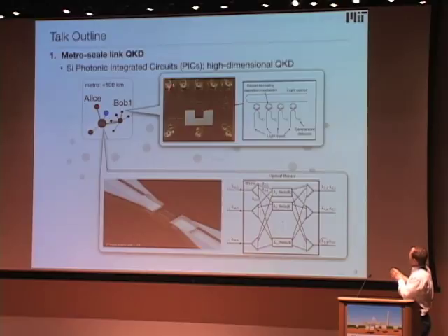And so here are two examples. Here is a photonic integrated circuit. The scale here is about 3 millimeters on the side, and you can see it mounted here into a circuit board. There are a number of RF connections going to this circuit, and also fiber connections that come off here from the side. Inside of this millimeter scale chip, you can have hundreds of modulators. And here is an example of what's in this chip.